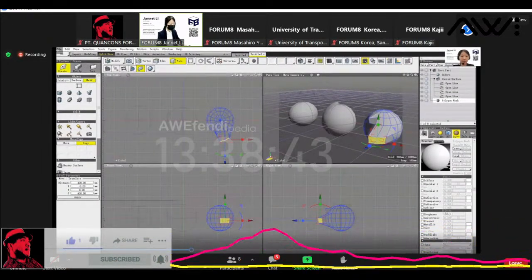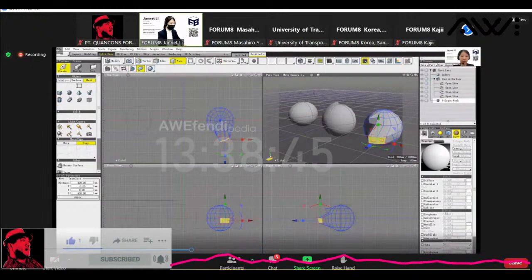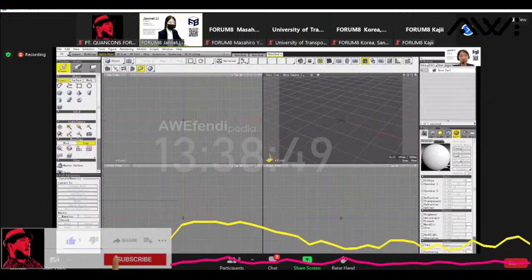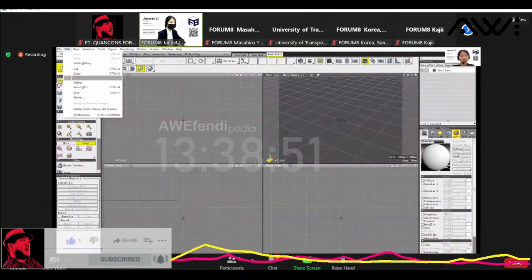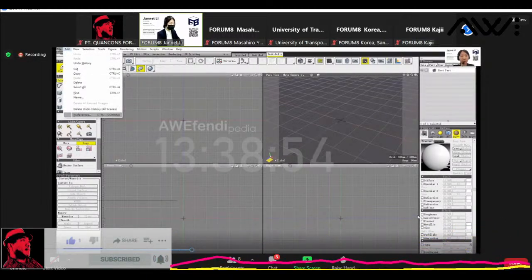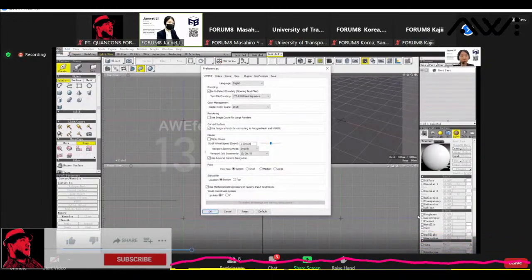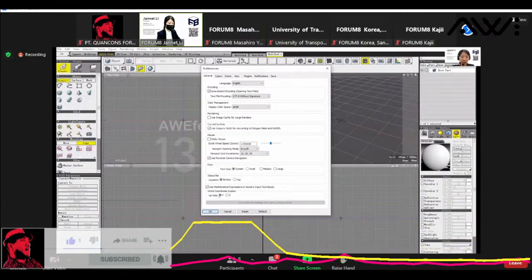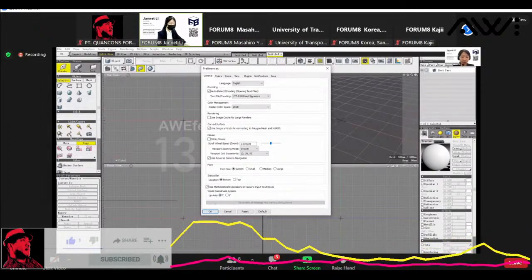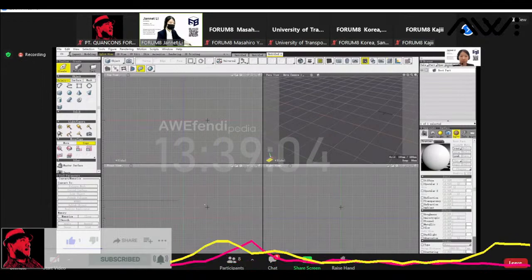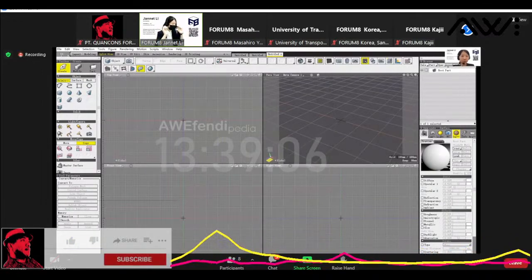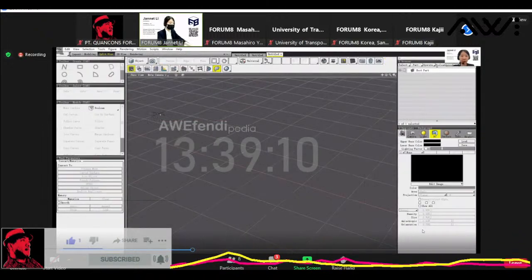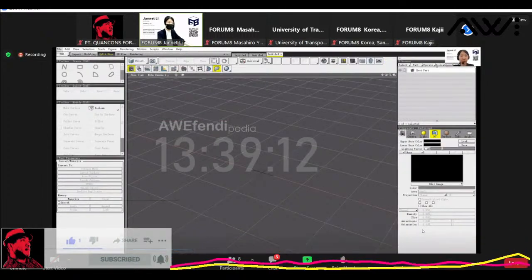So next, let's go into the sample shape modeling of the robot. Let's create a new file again. And please open up the preferences in your edit dropdown and make sure that the up axis is chosen as Y and not Z. Please choose Y as the up axis. Press apply and go into CAD. Go into the CAD mode.